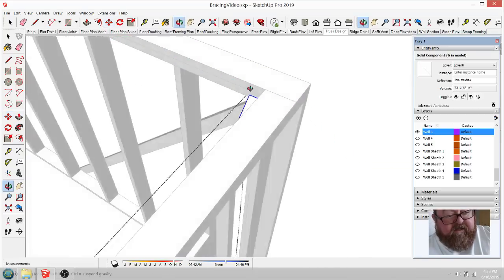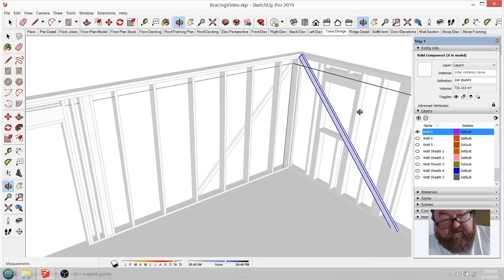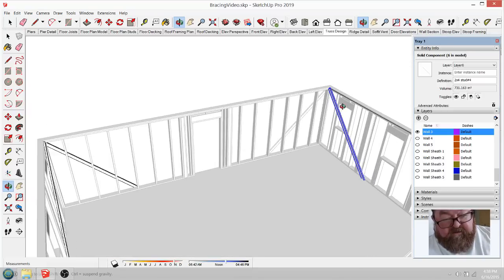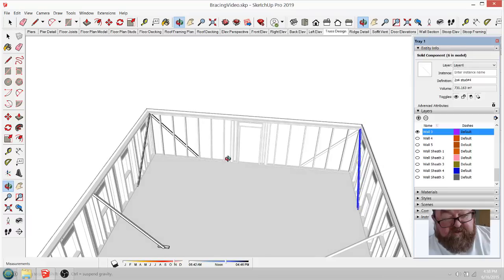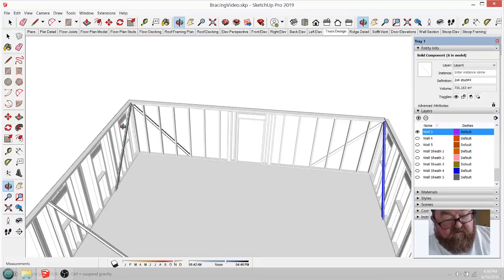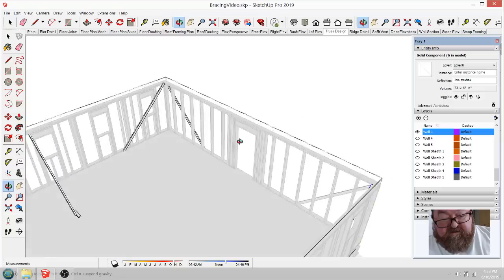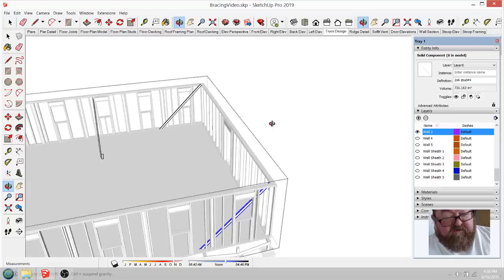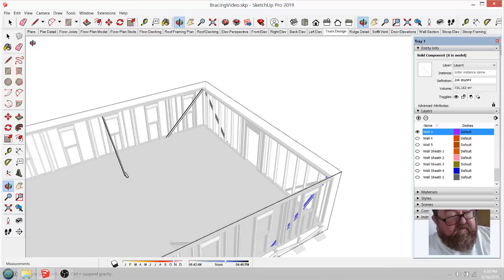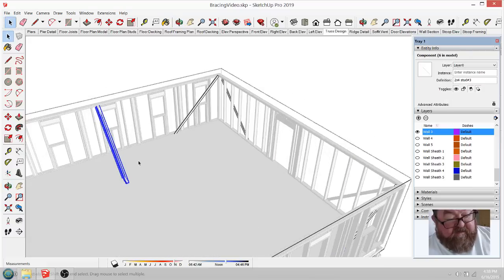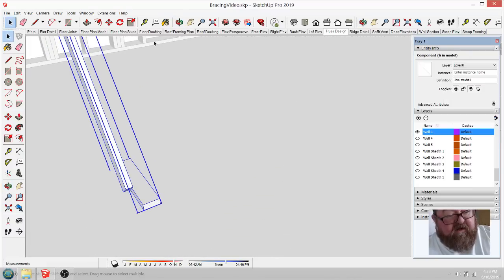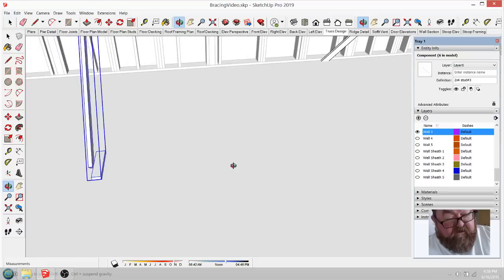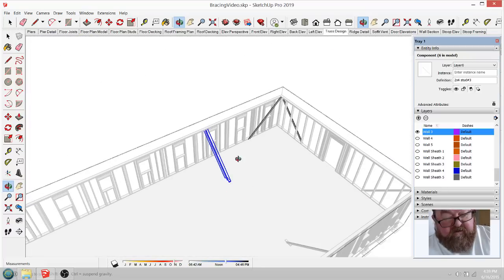Like that. There you go. Now you just stood that wall up, and you've got a corner brace here and a corner brace here. That's now bracing the wall. The walls are being racked back and forth this way. Now you're going to take one of these types of braces that have the block on the floor, and you're going to copy it and spin it around.